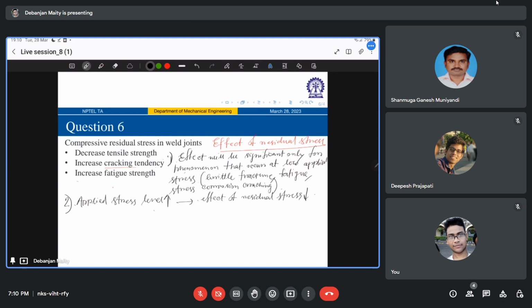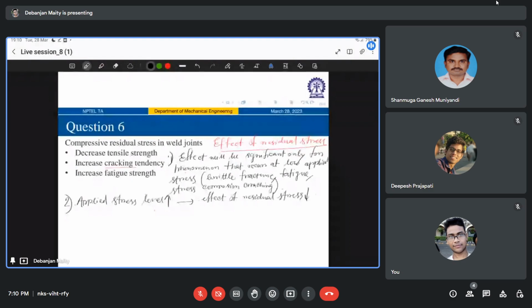What is the reason behind this? Because a higher applied stress overwhelms the residual stress by causing general yielding, right? And then what is the next one? These are a few points I want you to keep in your mind.